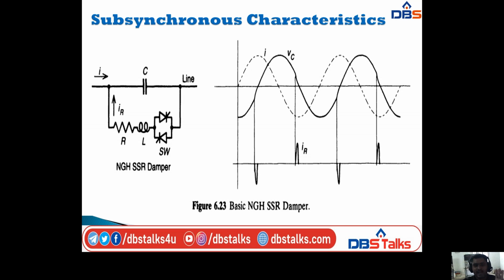By using this arrangement, we produce the waveforms for the line current I, the voltage across the capacitor VC, and the current across the resistor. In the first waveform, I am showing the line current as a dotted sinusoidal line. Then we have the capacitor voltage waveform, which looks sinusoidal but with minor changes. After that, the resistor current IR shows some spikes in the waveform.